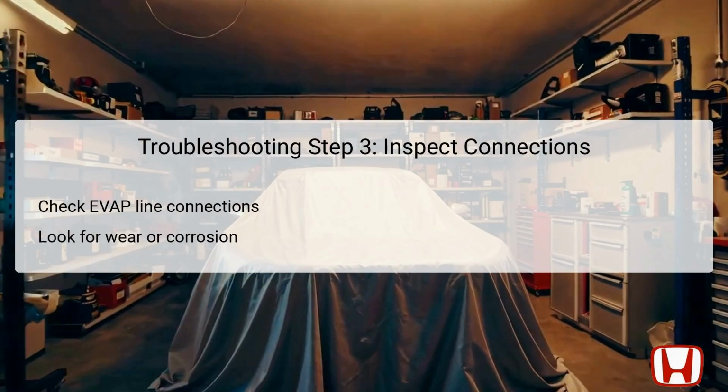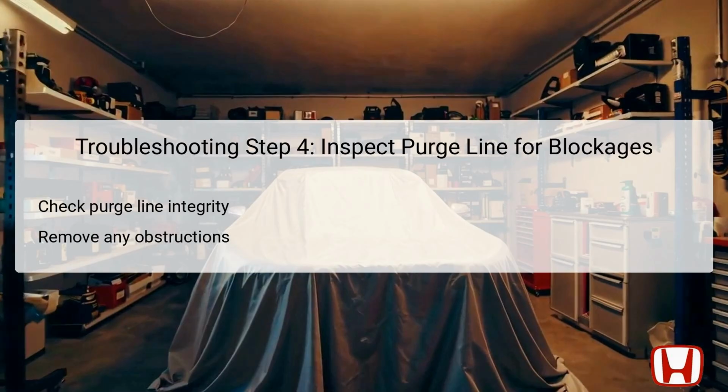with environmental standards. The fourth step in the troubleshooting process for DTC P145C is to inspect the EVAP canister purge line for any blockages or damages that may disrupt vapor flow. This involves physically examining the line that connects the EVAP canister purge valve to the EVAP canister.